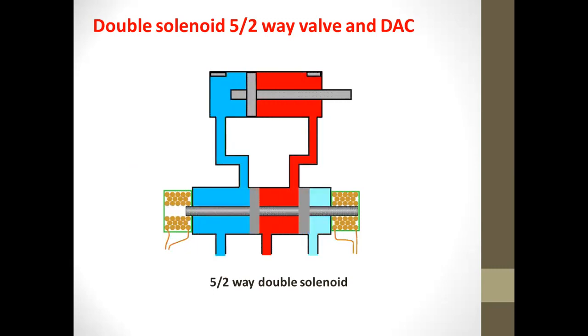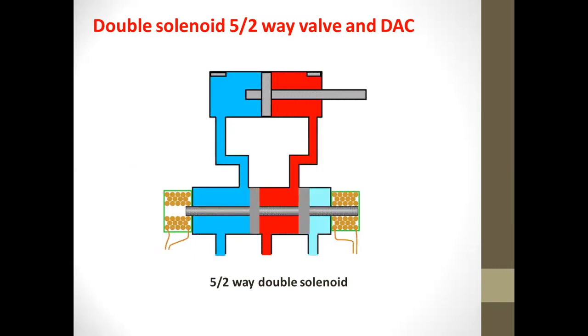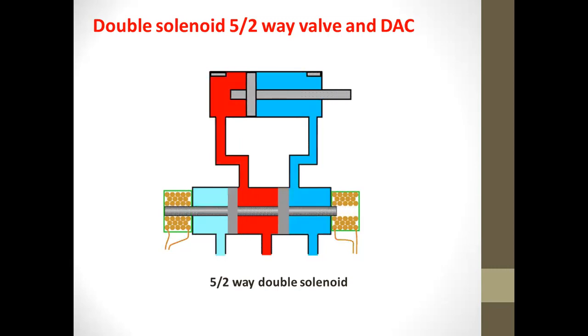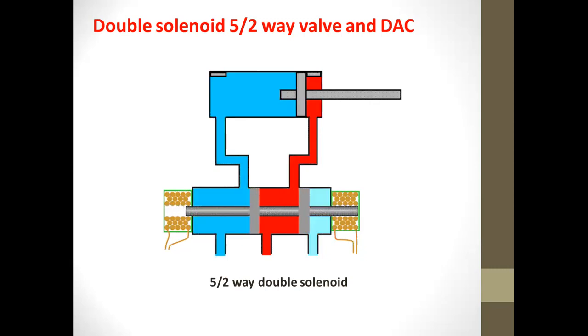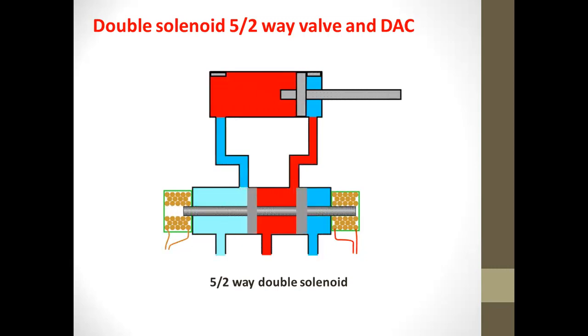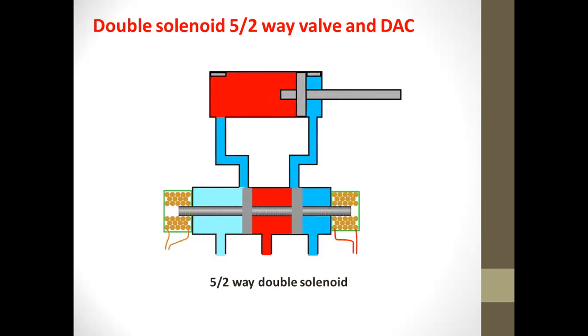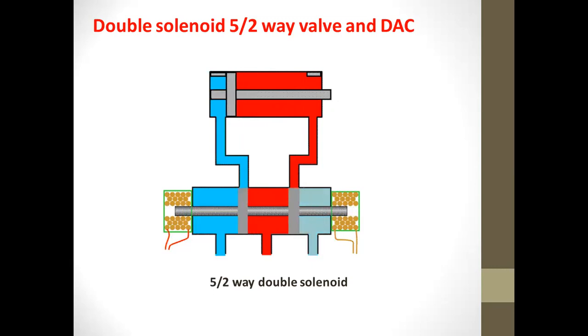And once the plunger goes back to the original position, in the case of the double acting cylinder, the air will flow in the reverse direction, allowing the piston rod to be pushed back, thereby enabling the cylinder to be in the retracted position again.